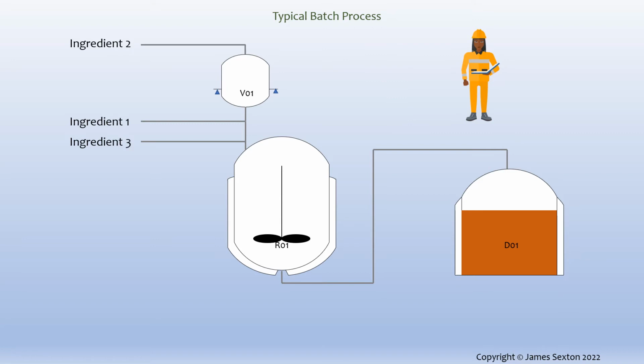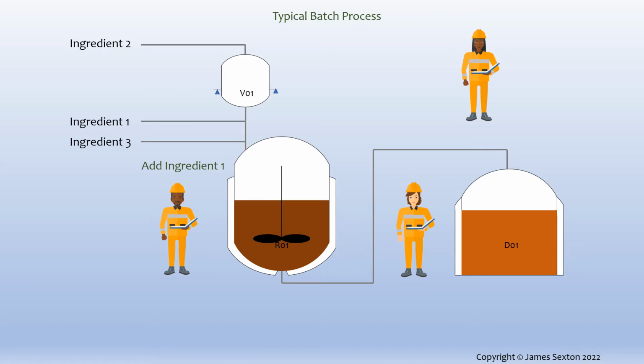So, consider the situation when the dryer has just been loaded from the reactor. If we isolate the dryer as a separate unit of equipment along with the dryer-specific part of the procedure, then those actions can now proceed independently. We can turn our attention to the reactor, which can also be controlled as a separate unit. This allows us to start on the next batch. Now we can see that the plant is better utilised.